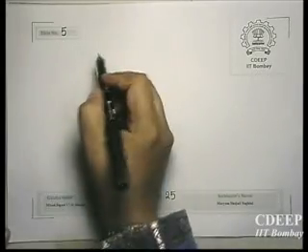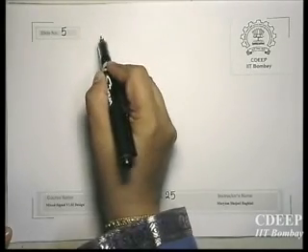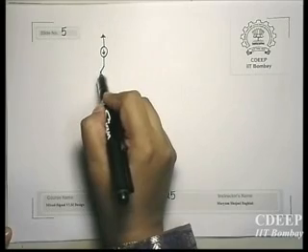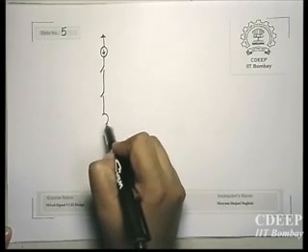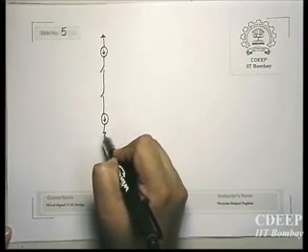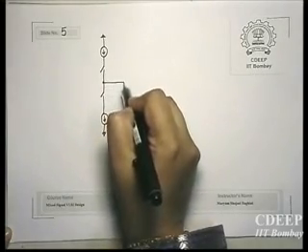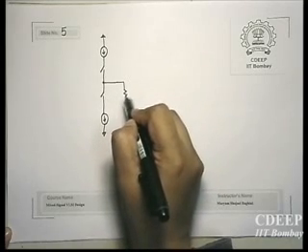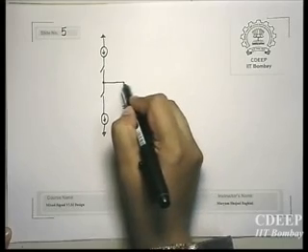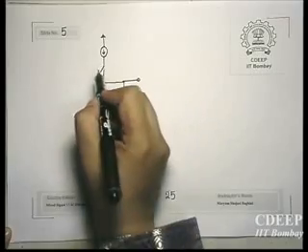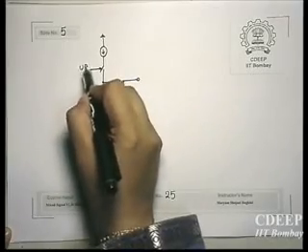This charge pump is a combination of two current sources connected to two switches, and then finally you will have another current source. So you have one source, one sink, and this goes to your RC. And these two are controlled by up and down.